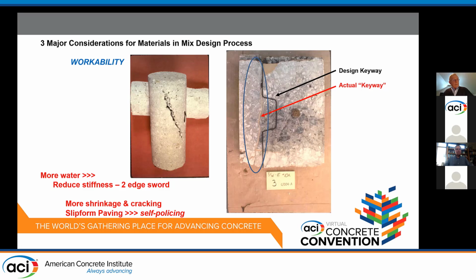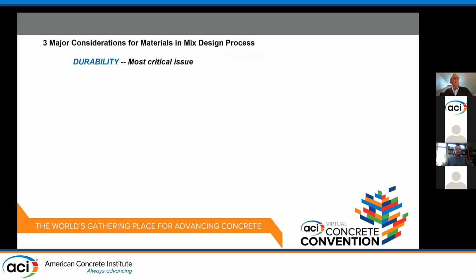The good thing about slip form paving is it tends to be self-policing. If the concrete won't stand when it comes out of the extruded finishing, then obviously it's too wet and the contractor needs to get that fixed.